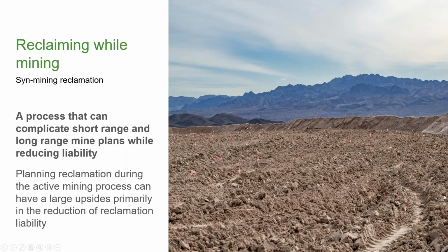The first category in the mining process is reclaiming while mining, which is syn-mining reclamation. This is a process that can be done efficiently during the mining process, where an operator is mining both ore and backfilling and actively regrading and placing topsoil and waste material in the backfill.